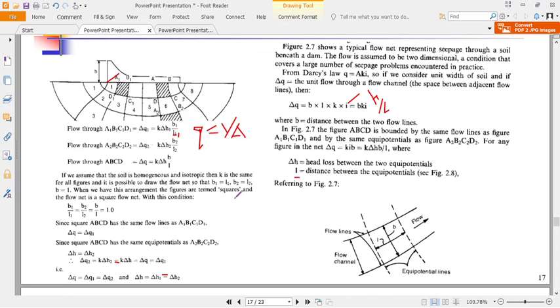The pressure difference from here up to here is a change in H. Let's consider this will be our H1. Remember, this is somehow inclined. There is a change in pressure which pushes the water to fall to this point, for the water to move through a distance of L1. Now the change in H1 over L will give us our i, where L is the length between two equipotential lines. Is that clear?